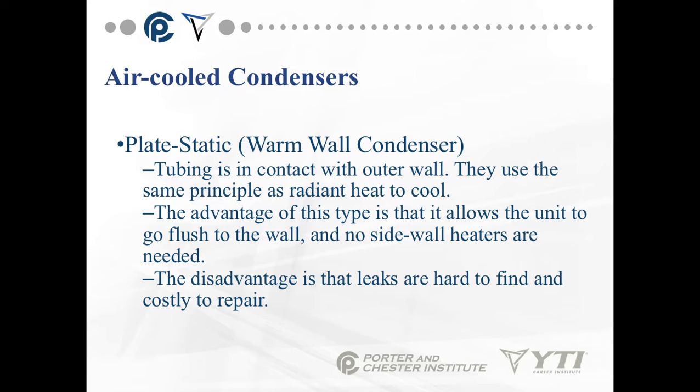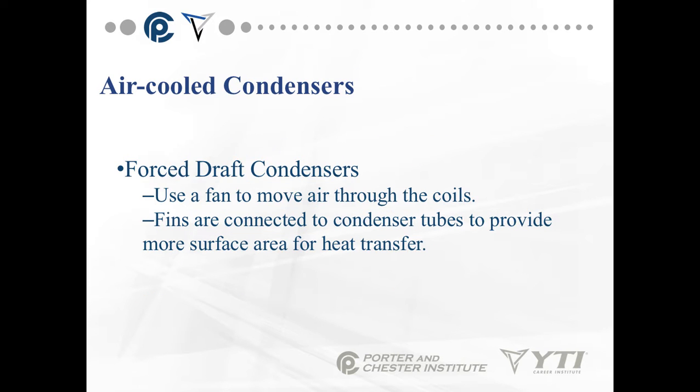Now, a lot of times you see these in freezers, domestic freezers. If you look at a freezer and feel the outside side walls of it when it's running, and it feels warm, that's because the condenser is actually built into the wall of that freezer.